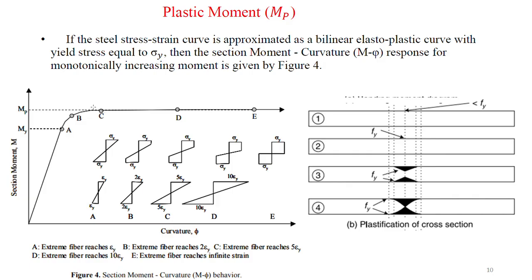This maximum moment we call the plastic moment. When it is reached, you can see in the diagrams for C, D, sigma y will be there, whereas the linear curve slowly reduces its length. When you reach A, there won't be this linear part; the elastic limit diminishes. There won't be any elastic limit, and the structure is going to break. These plastic sections mostly fail suddenly. There will be a sudden failure at the end, at the point A.